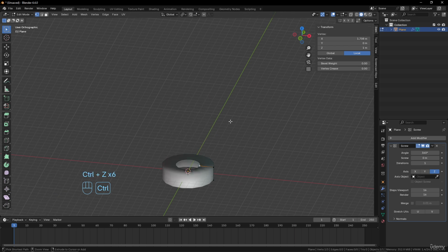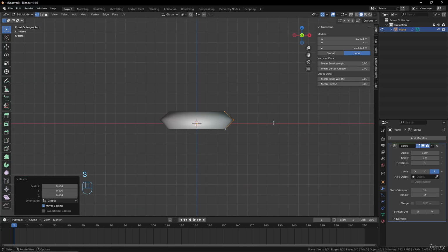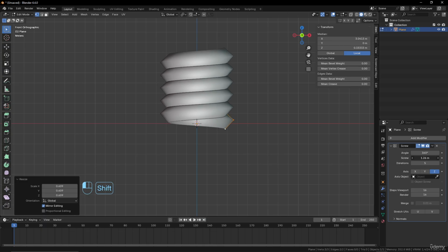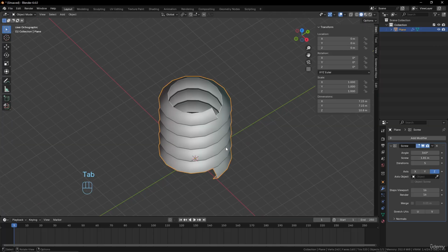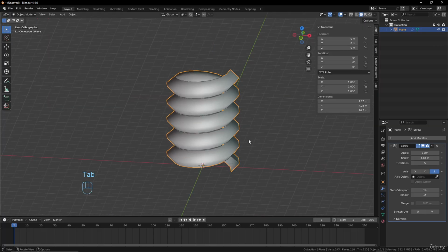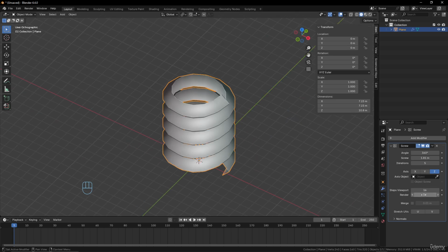And what is good with that one as well is that when you have this kind of shape here, you can create, for example, screws by increasing the iteration here and the screw option. So if you increase the iteration, increase the screw, you can see that it will create something like that. So very good to make everything that has a spiral shape like this. So very important to understand. You have the viewport, you have the render.